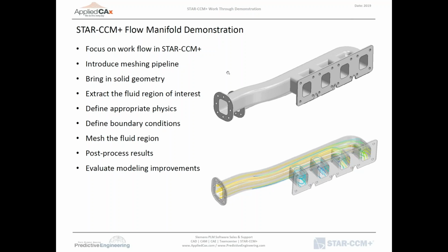I'm here today to give you a quick run-through demonstration of STAR-CCM Plus, focusing on the workflow. What we're going to do this morning is quickly bring in a 3D model and show how we can use the meshing pipeline within STAR-CCM Plus to extract the fluid volume of the part that we're interested in. Then we'll apply the physics, define boundary conditions, and mesh our fluid volume.